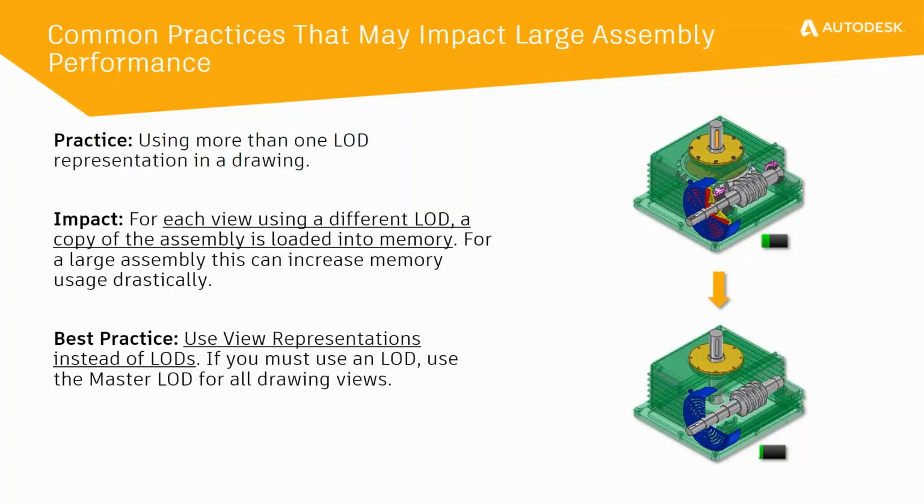Well, you can use view representations instead of LODs. By doing this, you're actually reducing the overall demand on your system to be able to load information in the background, whilst at the same time getting a similar or the same result.